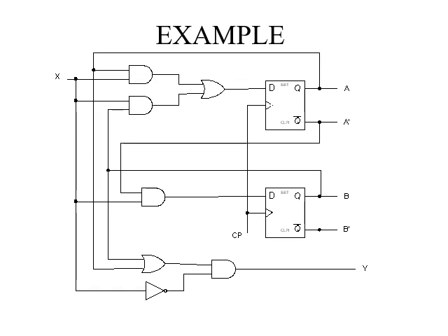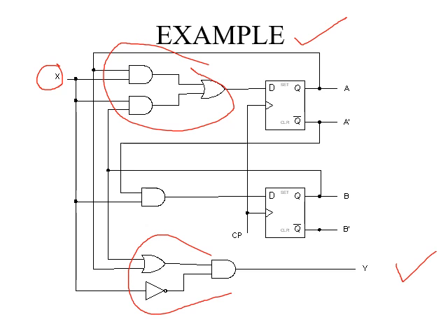This is a simple example which shows a normal FSM where our X is the input and here our Y is the final output. And in between we are using combinational logics, like this is a combinational logic circuit, this part is a combinational logic circuit.